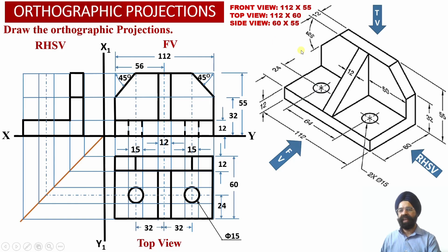over here. Whereas corresponding to this inclined surface, because this rectangular inclined surface happens to be inclined with respect to the profile plane as well, into the right hand side view projections onto the profile plane we are able to obtain the apparent shape projections corresponding to this inclined rectangular surface over here.